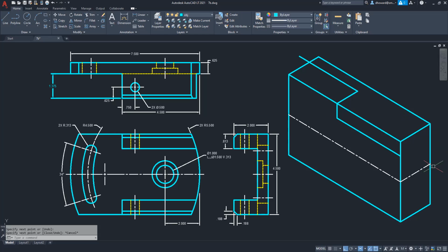So let's do the same thing on the bottom. So I'm going to click on the bottom corner, and I'm going to come up that distance, pulling upward in this direction, 0.813. And then I'm going to pull over in this direction for 0.25. Right? And then just straight down. Okay, I can trim that off if I wanted. Trim this one too.